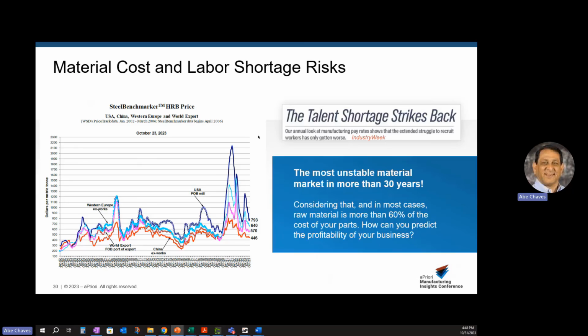And that is especially true because a casting typically has a better utilization than sheet metal parts. You can get in the 80%, mid 80s, high 80% utilization for castings, right? And so you are going to be using a lot less material and carry a lot less risk of being affected when this yo-yo of material prices happens, right?